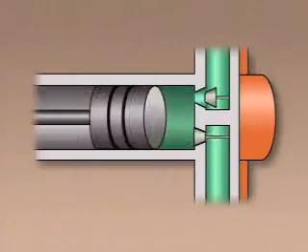On the discharge stroke, the piston squeezes the air into a small space, which raises its pressure. The increase in pressure causes the air to flow through the discharge valve and out of the cylinder to the atmosphere.